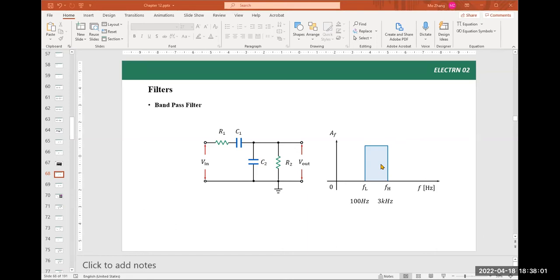The person's voice is in another frequency spectrum. If we know the frequency range of a human voice, and we only keep signals in that range and remove the sound outside this range, we can get a cleaner signal. The microphone can pick up a cleaner signal.